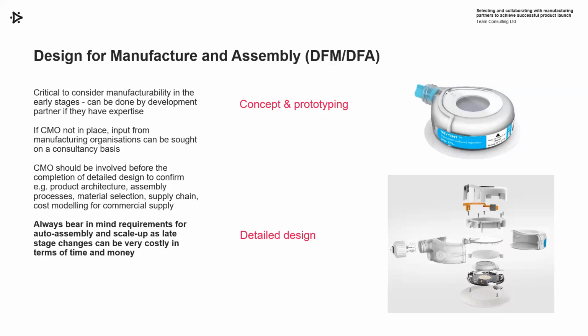Always bear in mind as well that requirements for auto assembly and scale up, you need to be thinking about them early on, because you don't want to need to introduce changes to allow high volume auto assembly solutions. You don't want to introduce changes late on that will implement that. If you can build those features in that you're going to need early on, then that's definitely preferred.